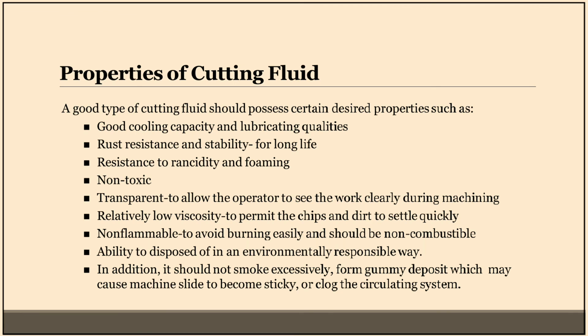relatively low viscosity to permit the chips and dirt to settle quickly, non-flammable to avoid burning easily and should be non-combustible, ability to be disposed of in an environmentally responsible way. In addition, it should not smoke excessively or form gummy deposits which may cause machine slides to become sticky or clog the circulating system.